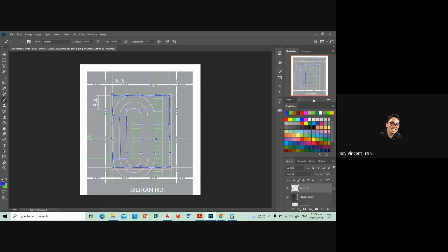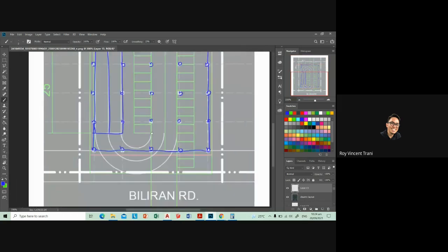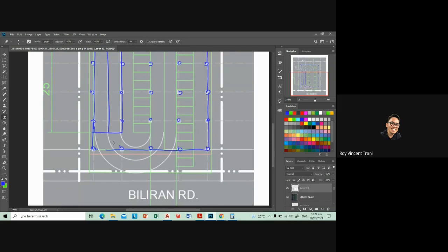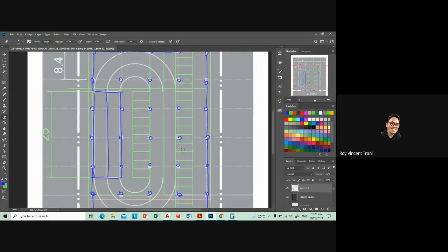And now I'm going to draw where to put your fire exits and miss one row of columns here. Fire exits and elevators. Okay, so hopefully that will go here. These extra columns I'm adding that are almost near the property line stop at the basement. These columns don't go all the way up to the ground floor. They stop at the basement. So that will be the column layout like that.